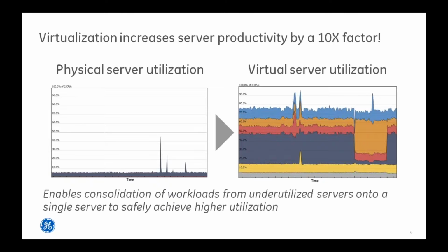If you look at this simple graph, what we're trying to illustrate here is that if you look at a typical system, whether it's a SCADA system or even some of the other systems that are used with your automation software, you'll often find if you monitor the CPU usage on a single system, it's actually not being used all the time, and you'll just get the occasional spike of usage here and there, really depending on the application load at any given time. Especially today with all the multi-core systems, you're just wasting all the resources of the hardware that you purchase by not making better use of it. In contrast, in a virtual server environment where you've got multiple sessions running on the same piece of hardware, you can essentially get the full usage of your hardware by leveraging virtualization.